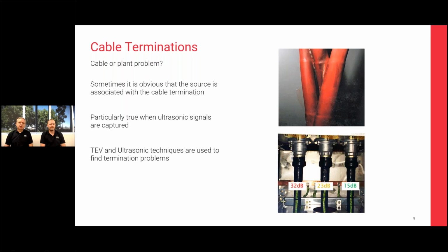Now, in order to test cable terminations, you don't need anything more than the handheld equipment that we've talked about many times, which is the UltraTEV type equipment, where we're testing for ultrasonic and transient earth voltage signals. These are perfectly adequate for finding cable termination issues.